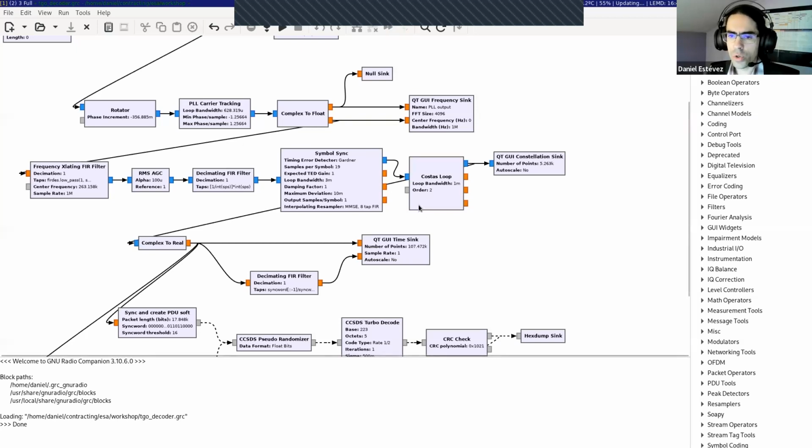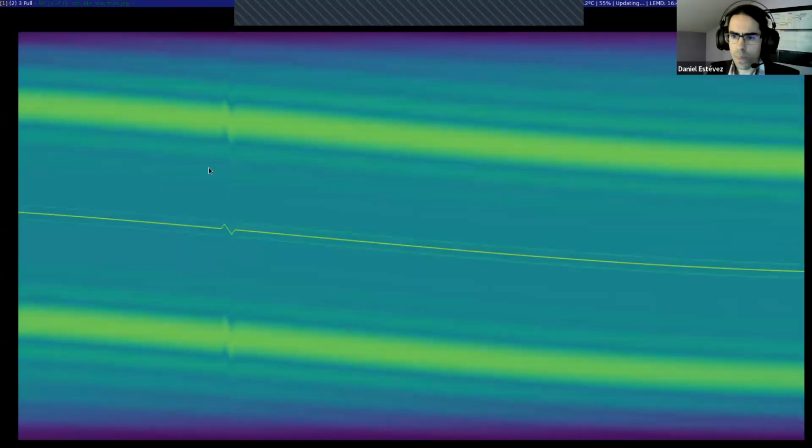And finally, there is a Costas loop. So what the Costas loop does is when we are translating in frequency this sideband, we might be making a small frequency error. So the Costas loop looks at the signal, recovers the suppressed carrier. So this doesn't have any carrier like this. But if we were to raise this to the power 2, we would recover narrowband carriers such as this one.